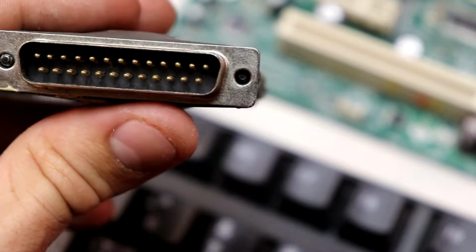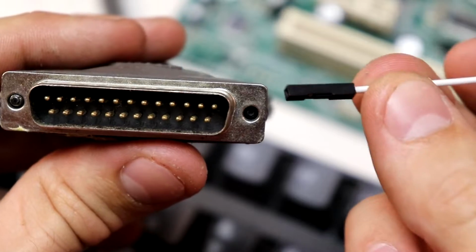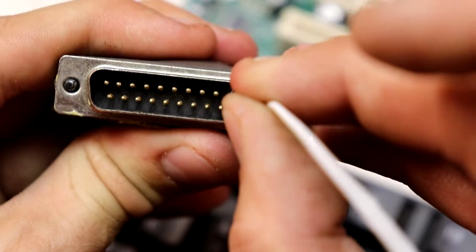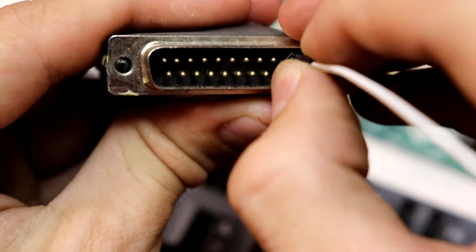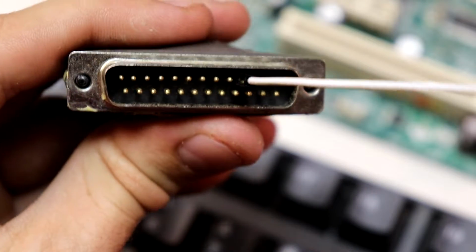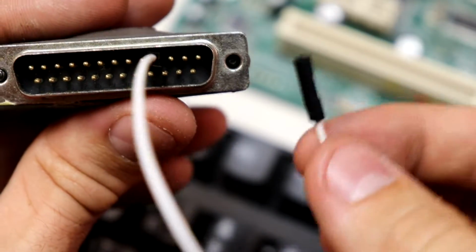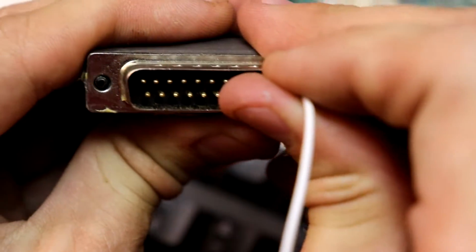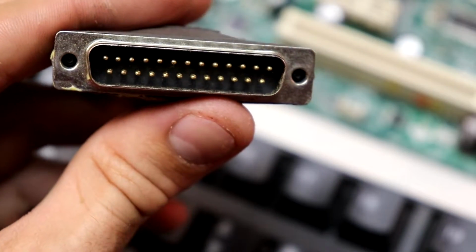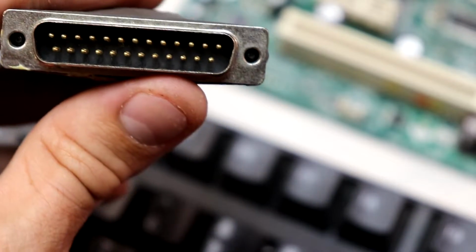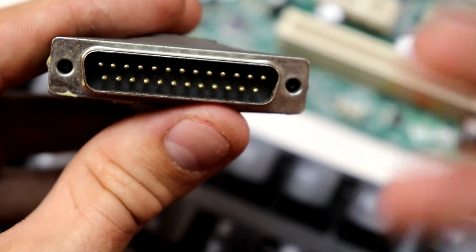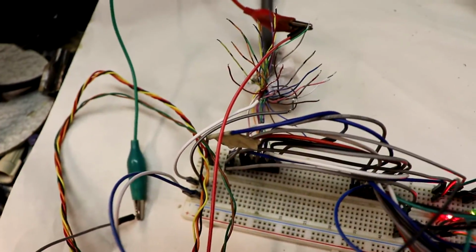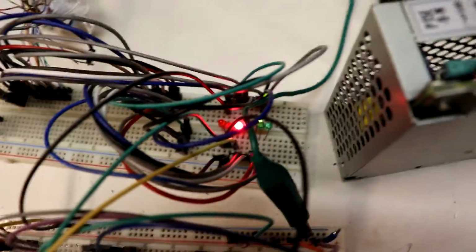And literally what I do is I take a piece of breadboard wire and I connect it to any pin that I need to find, and it should, without much effort, just stick in there. Should fit. And then I connect this end over to my multimeter, and I just do a simple continuity test. I literally test all the wires, and when my multimeter makes a beep, then I know I hit the right wire.